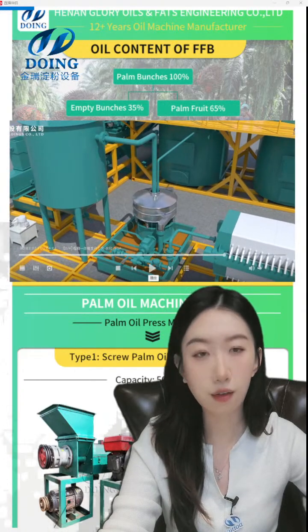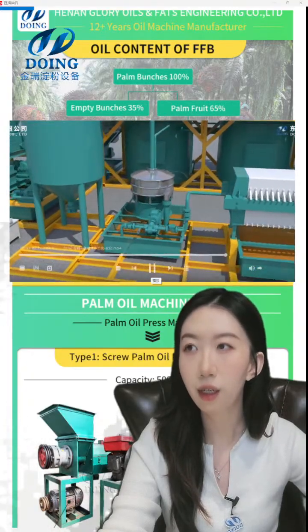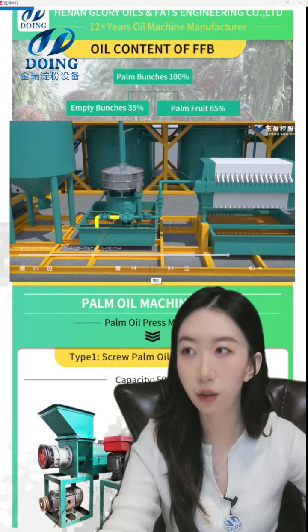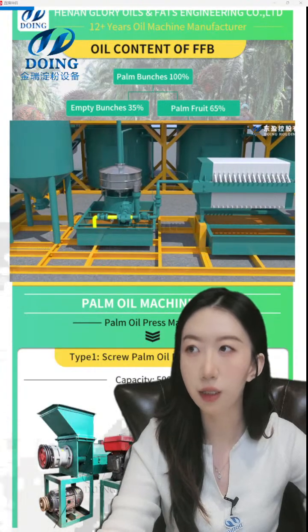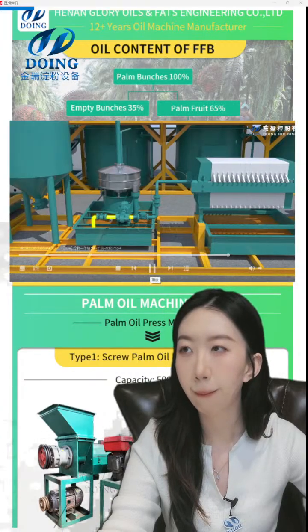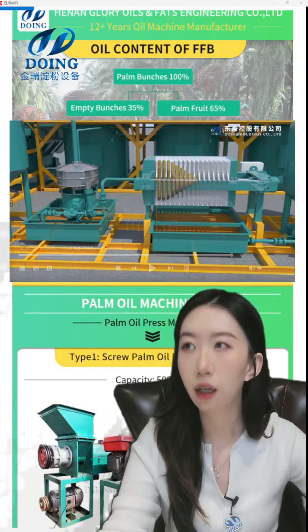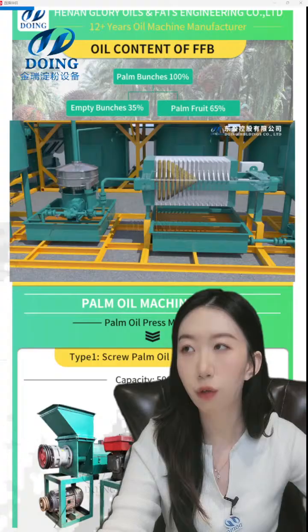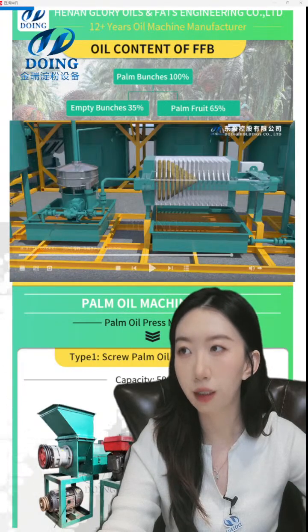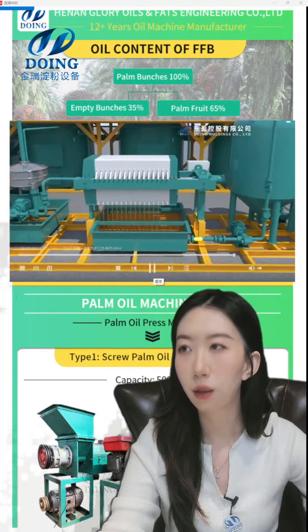The second clarification machine is this vibrating screen. There are 2 layers, and it can remove small impurities. And then the cleaner crude palm oil will flow down to the box and then be pumped to the plate filter.